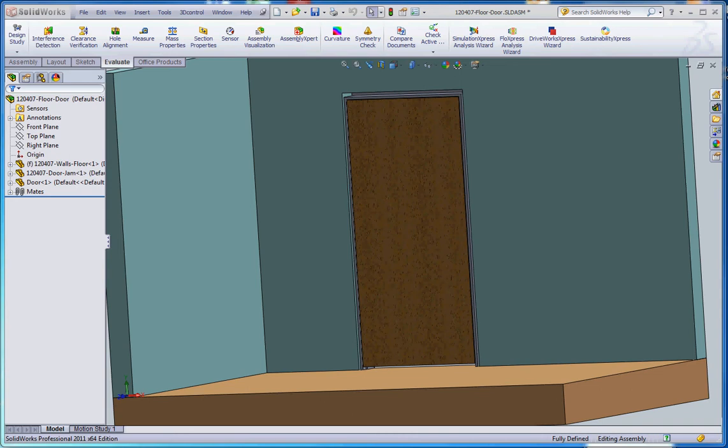In other words, if we want to make a configuration for a bigger door, all we have to do is change those two dimensions, our width and our height of the door, and everything should fall into place, with no more additional editing after that. It's all about being effective and efficient with our modeling, putting things together with the intent and the symmetry involved, so that when we make changes like this, everything falls in place with as little in the way of updates as possible. So we're going to design our door with that in mind.